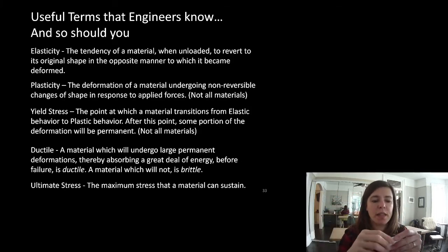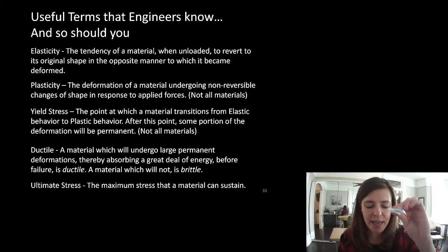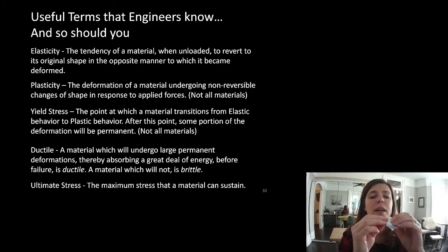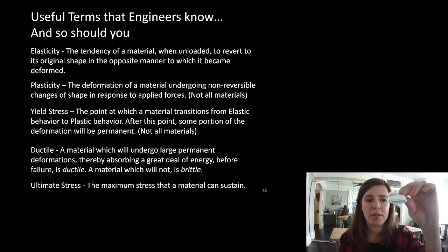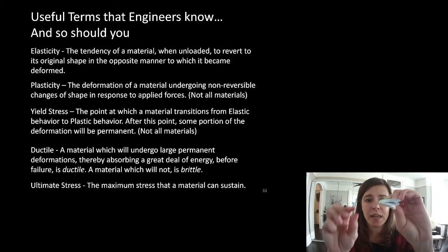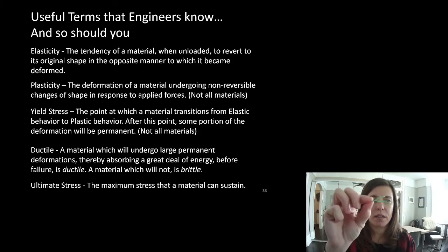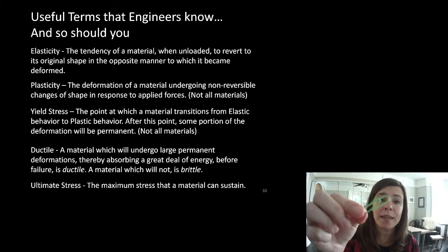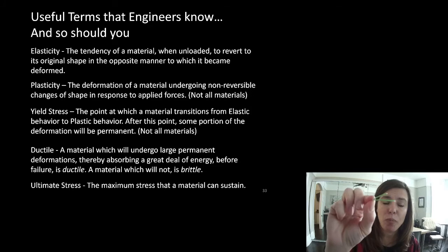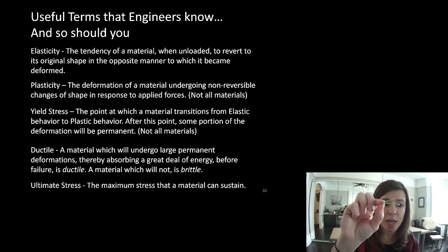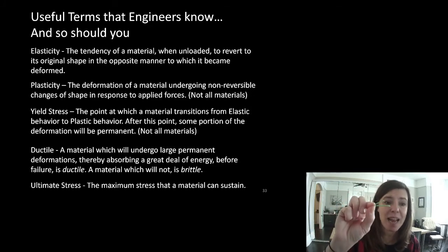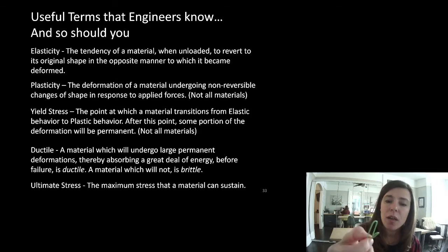I'm going to fold this paper up to something really, really thick. So this is a nice thick stack here now, and I'm going to take my paper clip and I'm going to stretch it, and I can get it over that paper. Look, it's done it, but when I take it off, look at that. It's got permanent deformation. We know with a little bit of paper, it snapped back to its original shape, but this time it didn't. It had permanent deformation. But it didn't fail. It's not a broken paperclip.